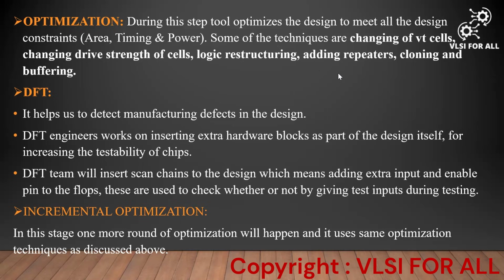Here we may have a doubt: what is cloning or buffering? Cloning means, if we have some AND gate cell that has to drive some load, let's say it has a fanout of 10, then a duplicate cell, like an AND gate replica, will be added so that it can be used to split that load equally. Likewise, this technique which we use for optimization is called cloning.